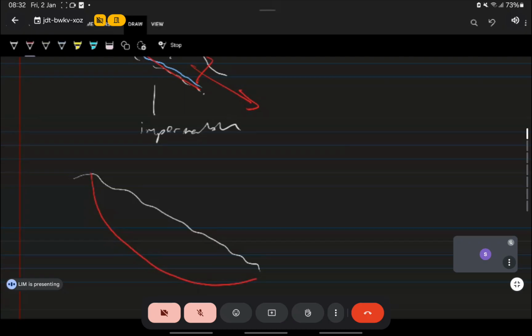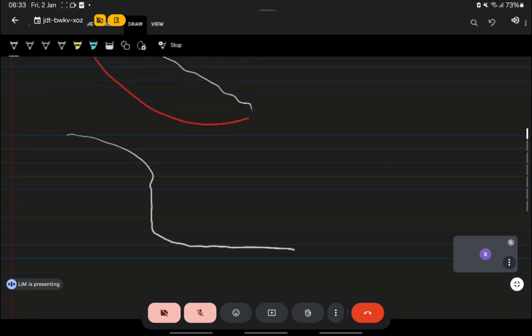To stabilize a slope, normally there are a lot of solutions. You can use geotextile, you can use nails. Or one option, if you have to cut the slope, if the slope has already failed, let's say you end up with a slope like that. Half of it has already failed, so maybe that part has failed. What you have to do to stabilize it then, one very common way, is you build a retaining wall to stabilize it.